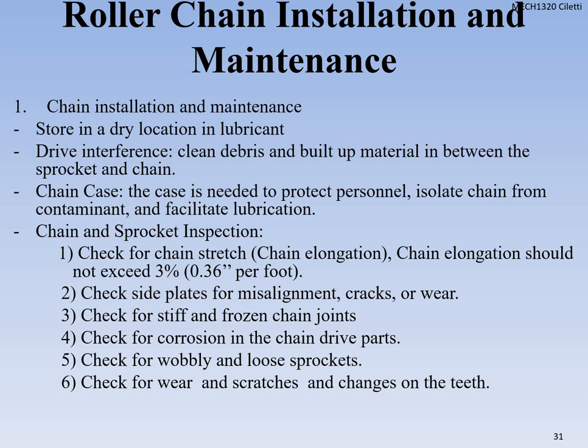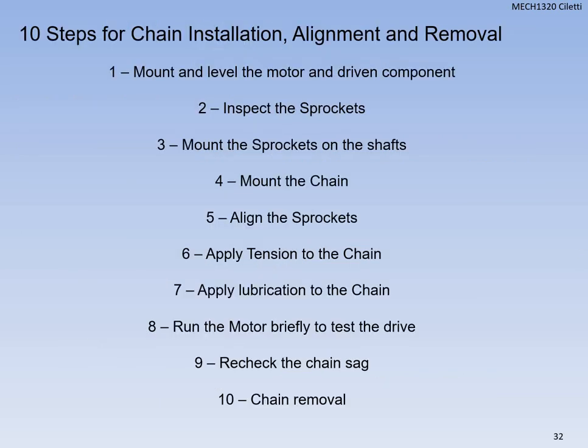Make sure you're checking to see if the sprocket's not loose. And you'll kind of understand more of these when we do the lab in class, because if you misalign it, the whole sprocket's going to come off and that sort of thing. So it is important for us to align sprockets. Okay, we'll have 4 points of contact when we do that. I'll show you. We're going to use a straight edge to make sure the sprockets are mounted correctly and in line.